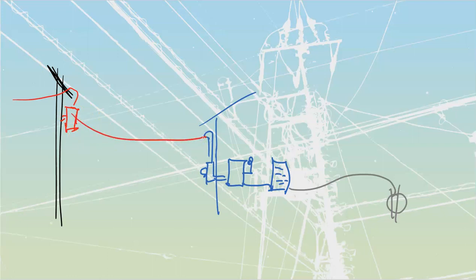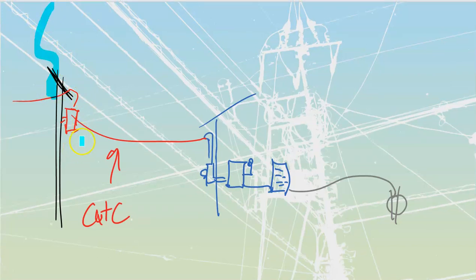This is what we would refer to as a category C type of location. Category C is going to be outdoor and service entrance installations. Cat C over here. Category C is obviously high danger, because anything like lightning is probably going to be directly connected to it. So it's going to have a fairly high withstand rating.